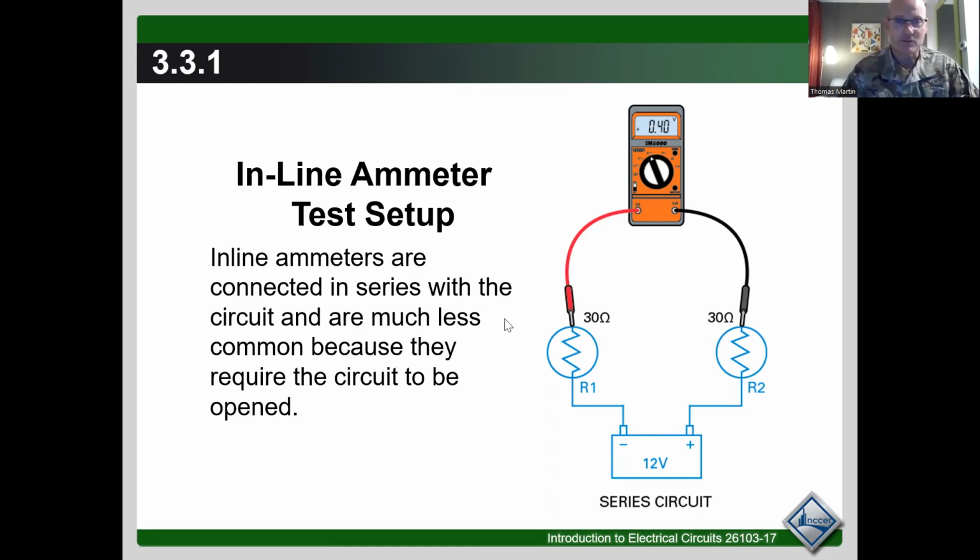That's why I called them inline ammeters. They connect in series with a circuit and are much less common because they require the circuit to be open.